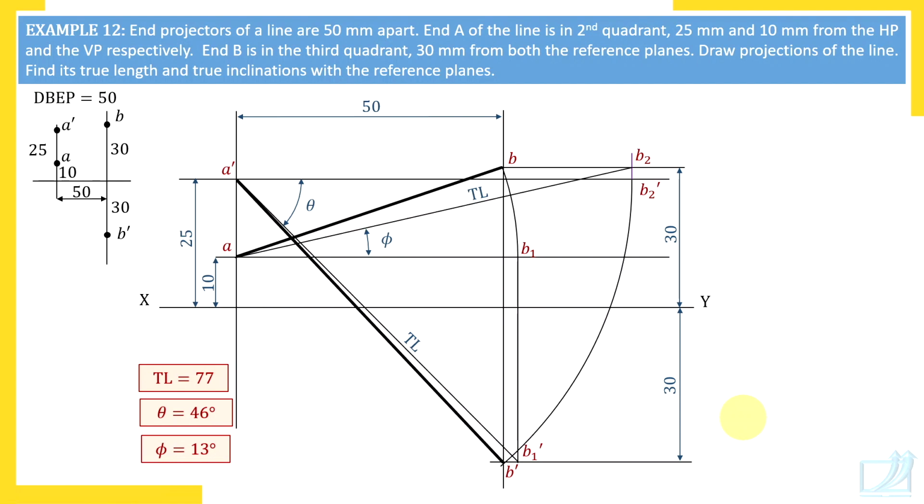So we have solved about 5 problems in this video. You must have realized that the basic procedure is to bring all 5 measurements on paper using the 6 views logic, draw horizontal and vertical lines through labeled points, rotate EL, PL, and if you don't get any extra point by rotating EL or PL, then you should use the true length.